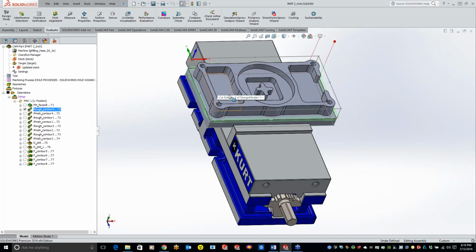Between the 2D, the 3D, we're not going to do gouge detection. We're not going to do stock target verification. Not a lot of good stuff there, but I mean, if you guys are just looking for something simple, fast, definitely use the 3D or the 2D. That option is out there, but if you guys are trying to get real proficient, you guys just want to see a quick toolpath, definitely just come over here and you guys can just hit the little checkbox and it's going to show you what's going on.